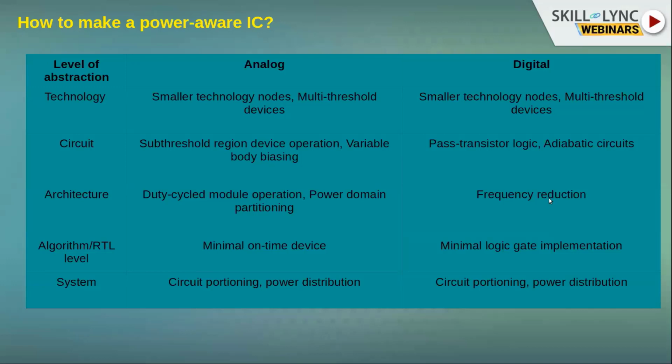And here I'll just give you a little idea on what is the type of power that is adding on to the entire power consumption. It's basically dynamic or switching power loss, and conduction loss, or the static loss. All these are the losses that amount in total to the power consumption of the IC. In the static power loss, there is the leakage current that happens when the system is not switching, it is on, and at that time, if any leakage happens, it adds to the power consumption of the IC.